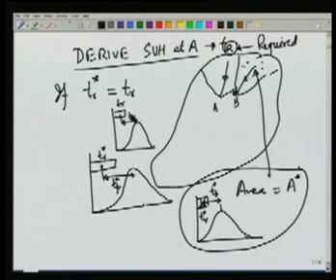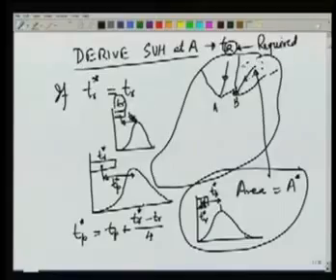and there is a relationship which is proposed by Snyder that TP star should be taken as TP plus (TR star minus TR) over 4. So this accounts for the difference in duration of the rainfall, the standard duration TR, and the actually occurring on the catchment area of B, TR star. So this helps us in obtaining the lag for the catchment area B. Now using these values, we can derive the coefficient CT for the area B.